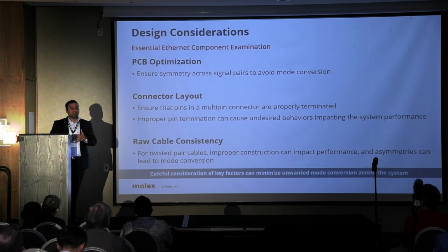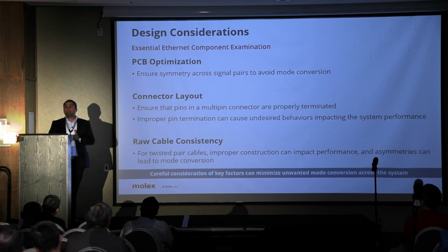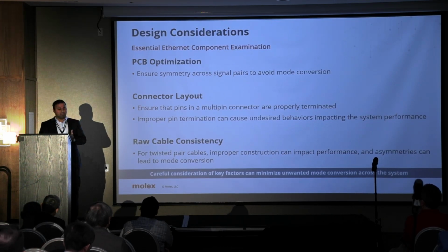From the PCB standpoint, symmetry is very critical. We need to make sure we have proper symmetry around the layout and that the system is balanced, to avoid any unnecessary mode conversion raised due to imbalances.